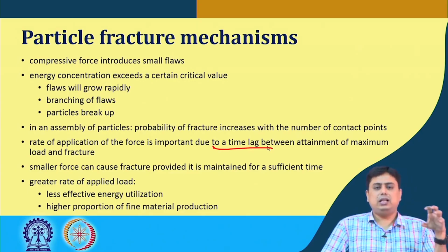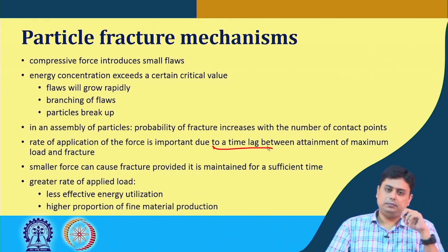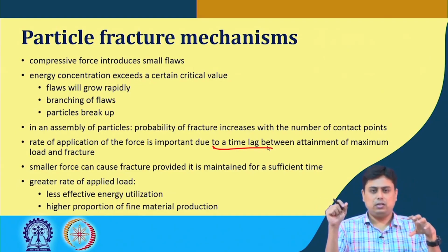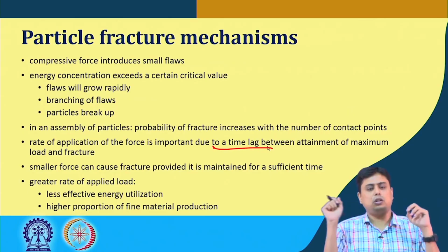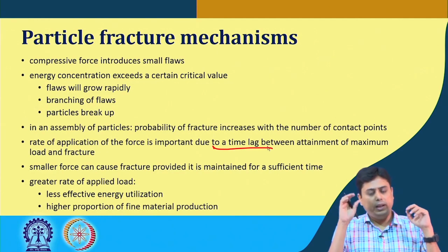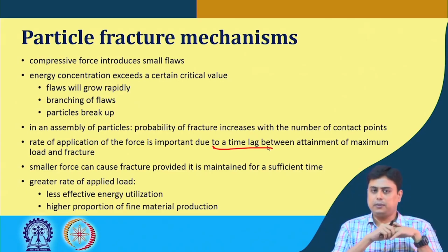Because if you remember the initial thought experiment, that you had a lump of material, you had an impact, the type of particles that we got, that we initially had very coarse particles in numbers, then the intermediate particles, and very few of the finer materials. So, when the intensity is increased, the solid particles basically break into small pieces, and the number of fine particle count goes up, but the size of the fine particles does not change. So, in terms of these finer particles, there is no such new surface creation happening.